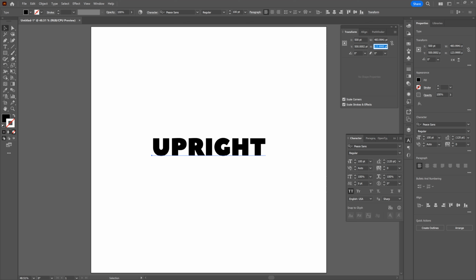We're going to enter in 86.602%. Let's go ahead and hit enter. Notice that squishes our type down just a little bit. That's all we need. Don't ask why, it just works when we do isometrics.